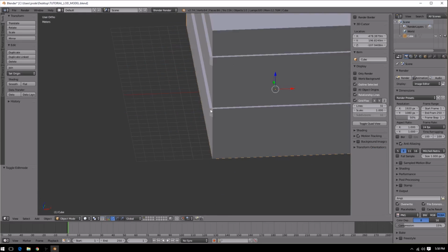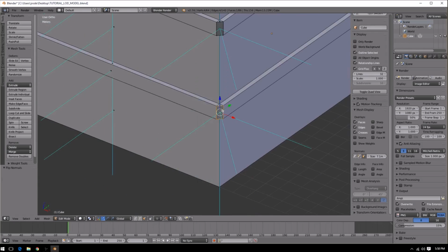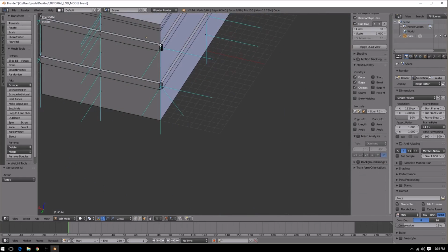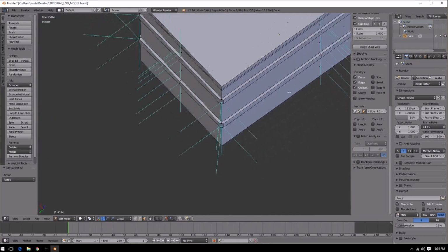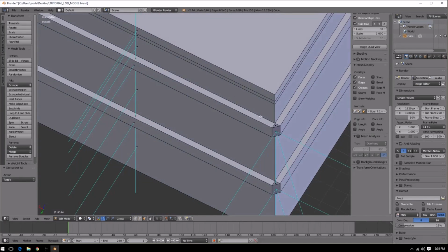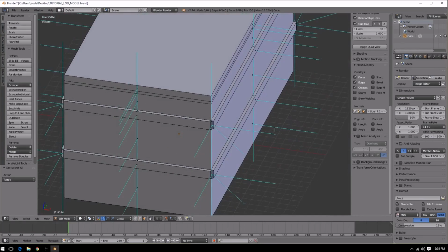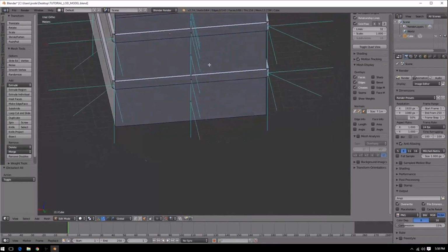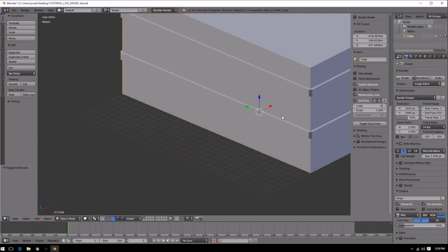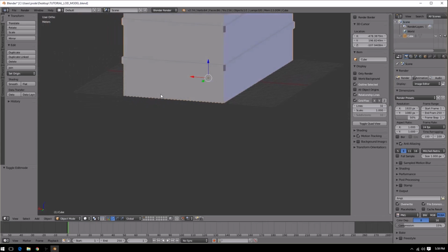Yes, so notice how once we flip these normals, they stop being black, like over here. You can see that they're shaded correctly. Okay, so we'll do that one, and just scroll around and do all of these black chunks. You never want to see these black faces or black lines in your mesh. That means you're going to see through parts of your mesh, and this is not good. Another element of modeling is making sure you're very detail oriented and stopping every now and then and double, triple, quadruple checking your work. It's a lot easier to just model things correctly than to mess it up and go back later to try to fix it. Okay, so you can see these are dark, but that's just the shading in Blender playing into it, and we don't have black faces anymore, which is what we want.